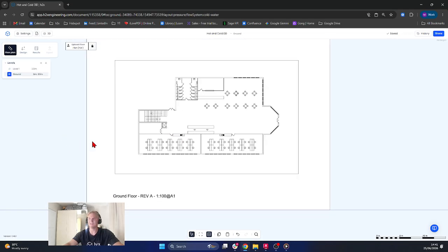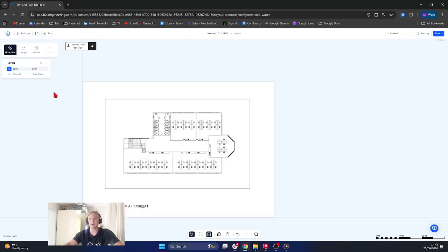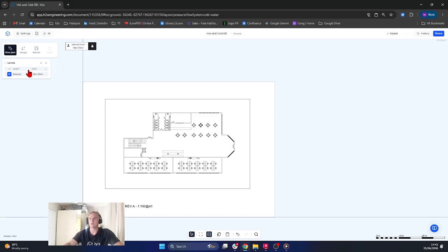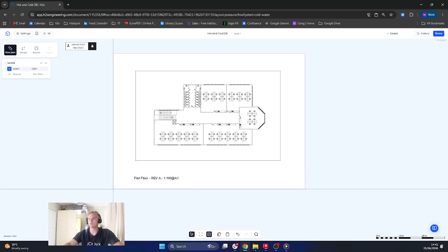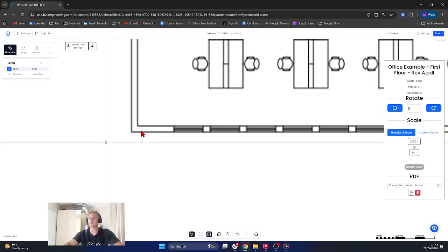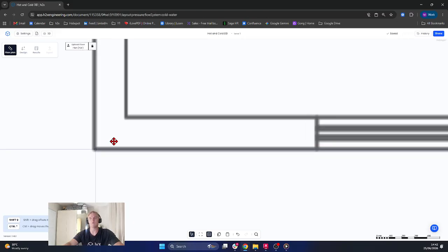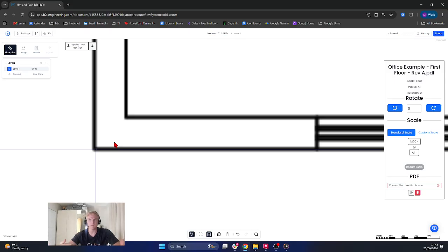Now, to align or not to align would depend on whether you have a standard sheet setup like we have got in these different revisions. Now, this blue crosshair is what I would use to align them within h2x, but it also serves a purpose at our later export stages, like when you want to export it into AutoCAD or into Revit.